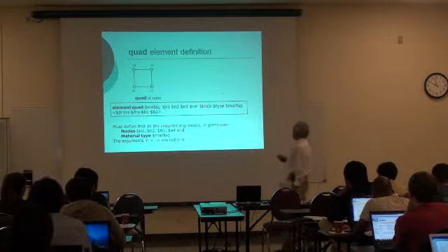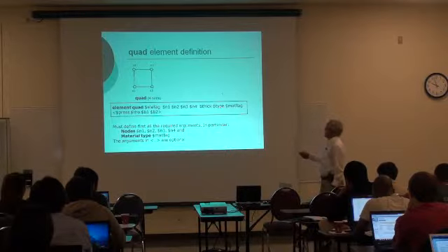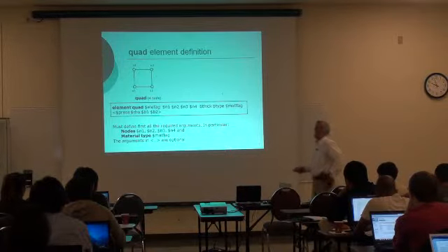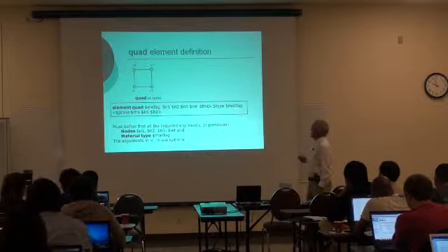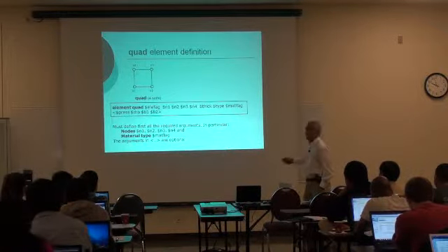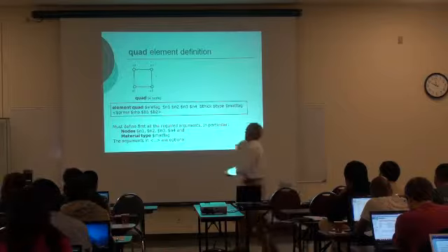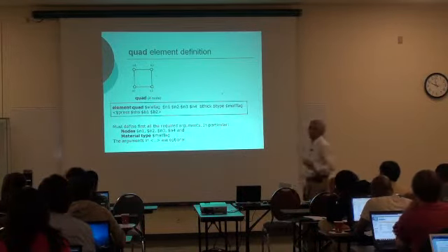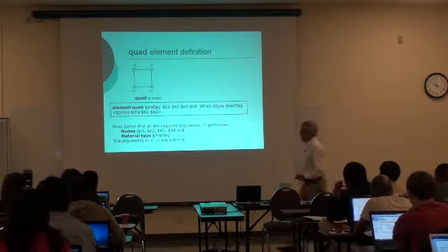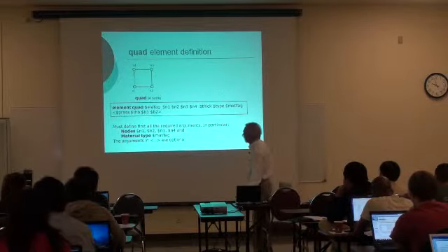You also define the thickness, the type of the two-dimensional element that you have, if it is plane stress or plane strain. Also the material tag that is associated with the element. And then you have some optional additional parameters like body forces, etc., that you can include in the definition of the elements.